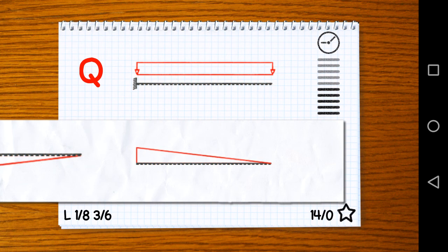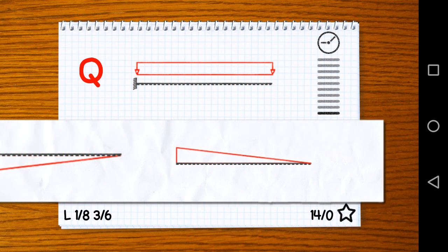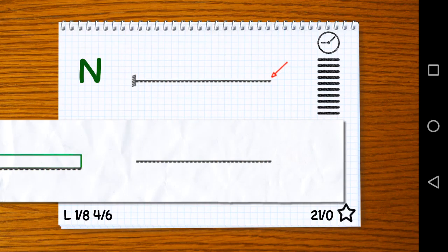What happens? At the free end first, we don't even have the load yet, because this is a distributed load. It's going to increase linearly. First it's 0, and then we go downwards in the direction of the load, so going downwards with a linear increase.